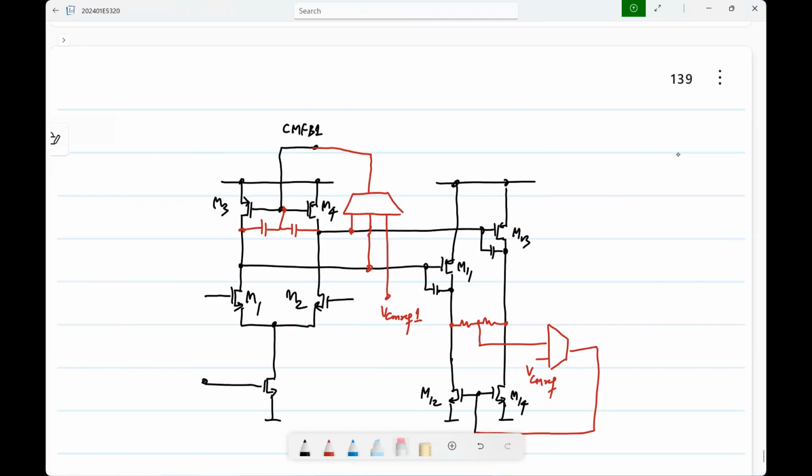So add transistors in. So basically, the general idea is right. So if you want lesser GM for the common mode feedback than in the differential, it's actually quite easy to do. What you can do is, you can split, sorry, these are not the same gate voltages.